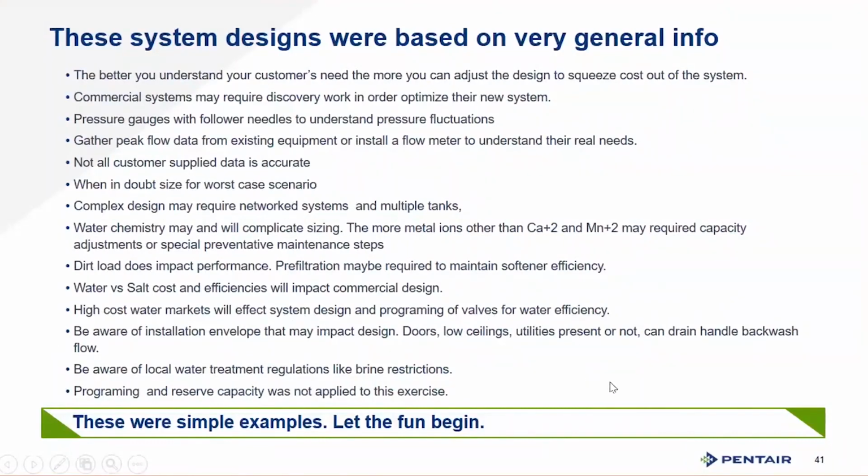Be aware of installation envelope. Doors, low ceilings, utilities present or not, can a drain handle a backwash flow, etc. Those factors matter because we're putting this into a building that already exists. Beware of local water treatment regulations like brine restrictions that limit the amount of brine you can use. Waukesha, Wisconsin, lots of counties and towns in California are brine restricted. You're limited to 3 pounds of salt or exchange tanks only.